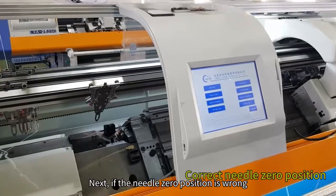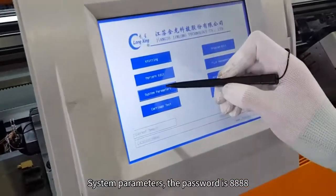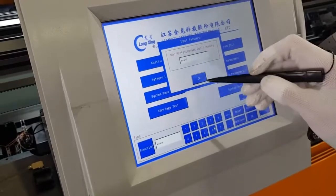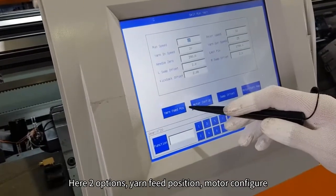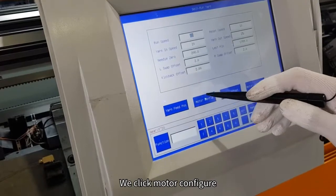Next, if the needle 0 position is wrong, we can change it. System parameters, the password is 48. Self-run yarn. Here are 2 options: yarn feed position and motor configure. We click motor configure.